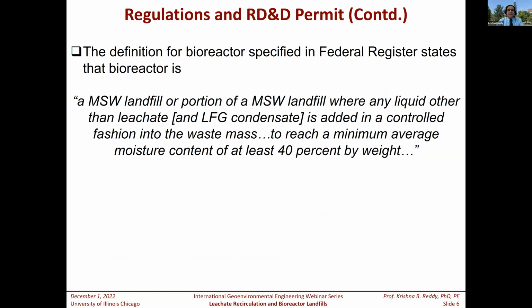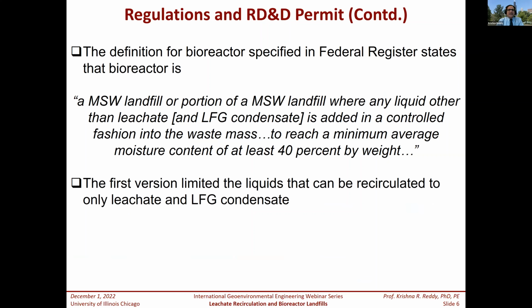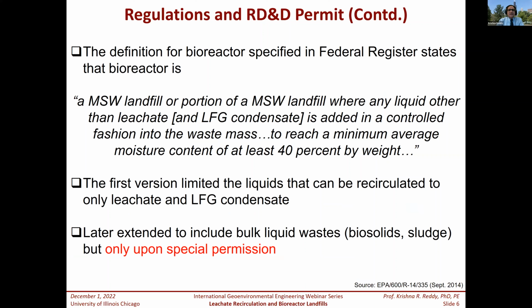And in the regulations, you don't find a universally accepted definition for bioreactor landfills. One definition that you can find in the regulation is given here. It says: an MSW landfill or portion of an MSW landfill where any liquid other than leachate is added in a controlled fashion into the waste mass to reach a minimum average moisture content of at least 40% by weight. So this is one definition, but there are no universally accepted definitions that you can see.